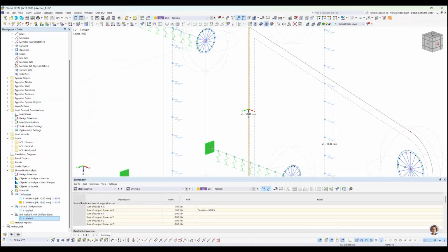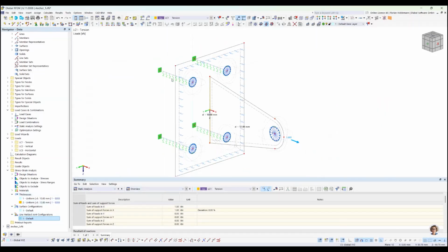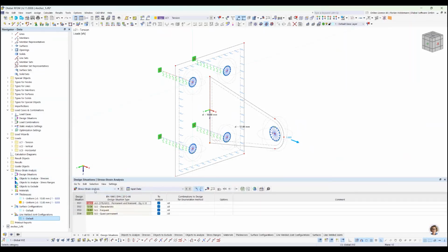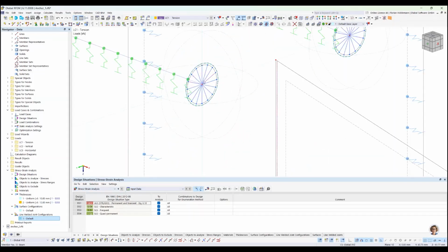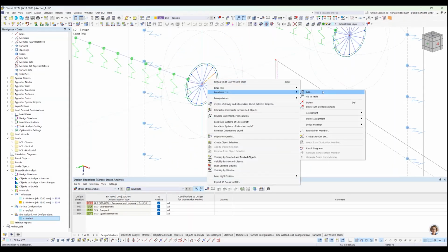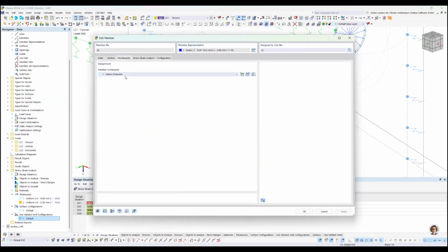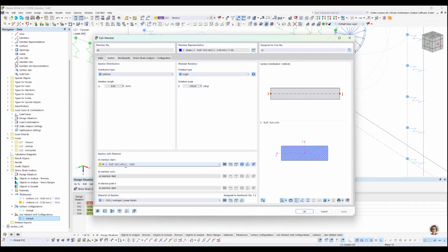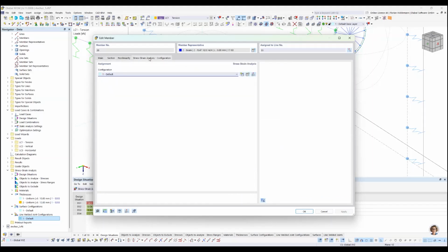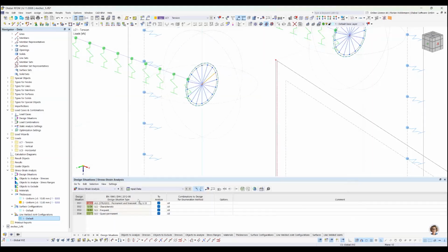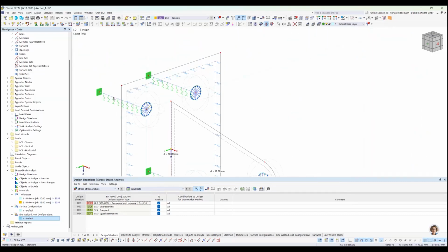Also, the last configuration is about the beams here. You can also activate these beams, and I will show you this in the example. If you switch here to the stress-strain analysis, obviously we don't want to calculate all these other members we have here because they are only to model the forces on the plate. Yeah, we can have a look at them. These have a non-linearity and they fail if they get tension forces. So they only apply pressure forces and have a custom flat cross-section. And we don't want to have them in the stress-strain analysis, but we would like to see the other members.